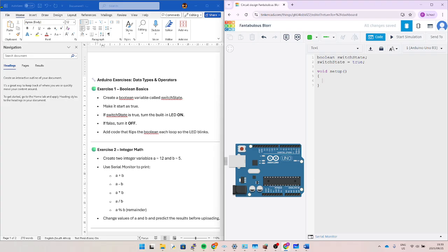Type in here. We're gonna basically set up the components. It starts with a P. Specifically, what's the name? Your pinMode. Key thing to note, where you put your capitals matters. Your pinMode, right? And it's gonna be the LED_BUILTIN, and it's gonna be an OUTPUT. Right.